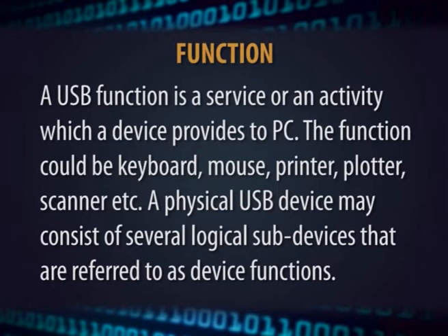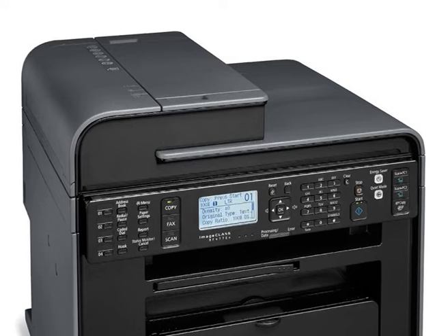Function. A USB function is a service or an activity which a device provides to PC. The function could be keyboard, mouse, printer, plotter, scanner, etc. A physical USB device may consist of several logical sub-devices that are referred to as device functions. One device may have two or more functions, such as a multifunction device that may have a printer and a scanner and a fax machine, all operating out of a single USB cable.